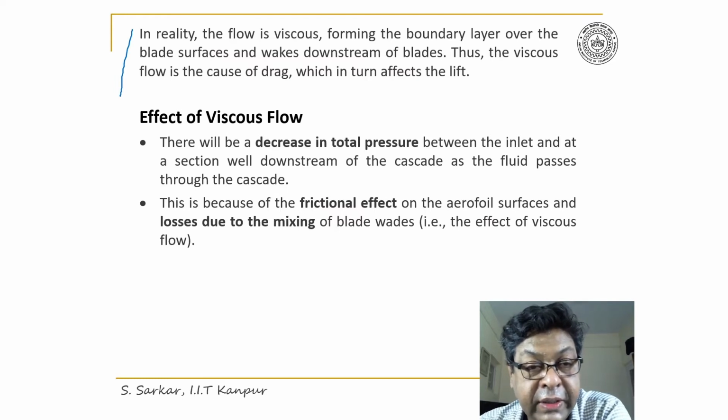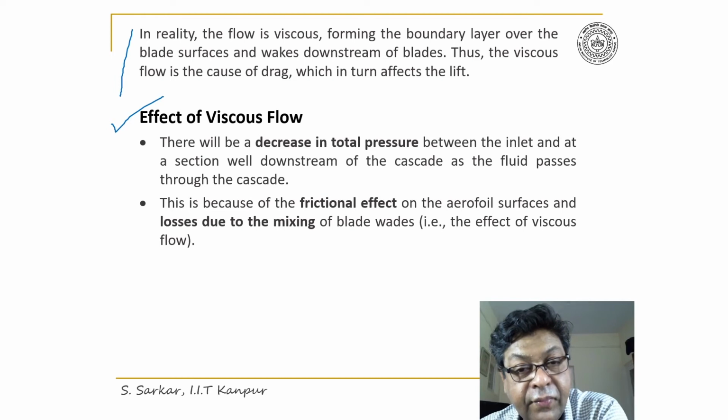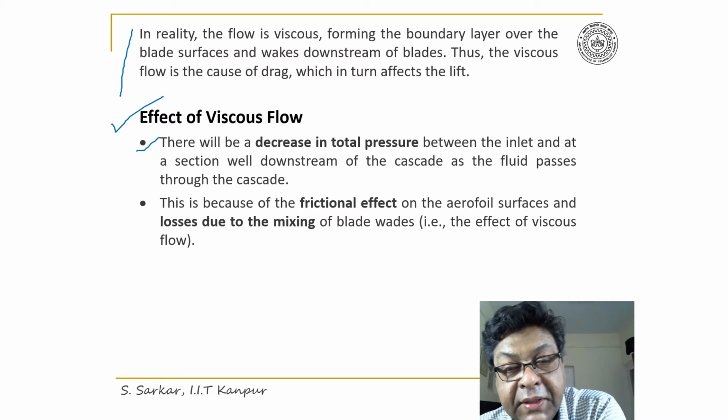Now, what will be the effect of viscous flow? There will be decrease of total pressure between inlet and at a section well downstream of cascade as the fluid passes through the blades.